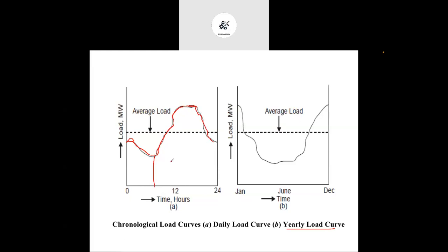So this is just one type of load curve. This load curve again depends upon the customer type, what is the requirement of the customer. It is also going to change with respect to the time period. Here we are considering the day, that's why this type of load curve is there. Generally this type of load curve is for commercial buildings. If you consider a residential building, this load curve will be different.